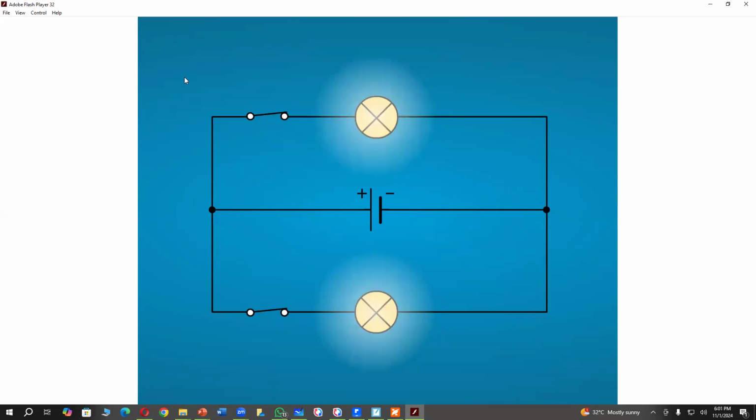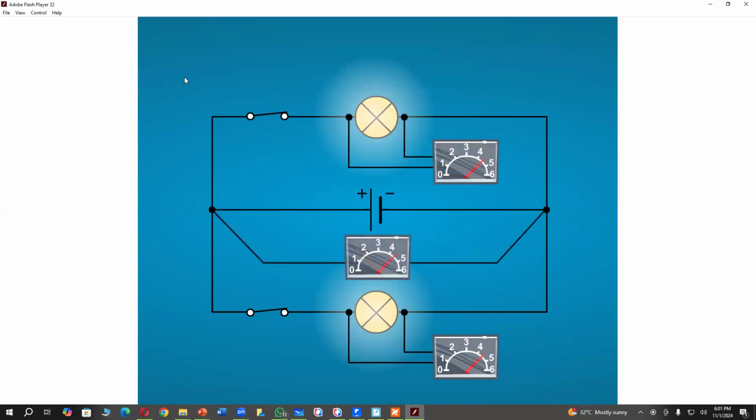This method of connecting electrical devices is called a parallel circuit. The parts of the circuit which are connected parallel to one another are called circuit branches. When electrical devices are connected in parallel, the voltage across them is identical. The voltage across a bulb can be measured directly at the ends where the bulb is connected and, as we can see here, also across the ends of the circuit branch which contains the bulb. In both cases, it is the voltage between the junctions in the circuit which is being measured. So it is not surprising that the measurement of the voltage across the 2 bulbs provides the same reading.